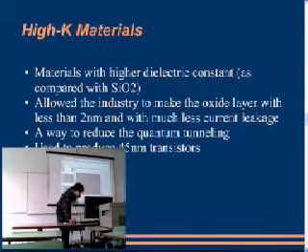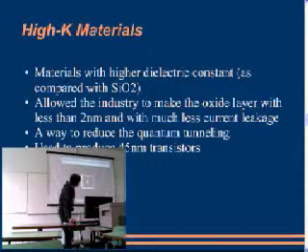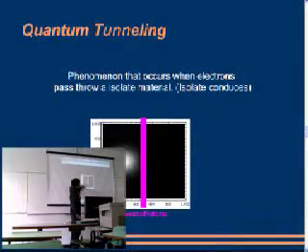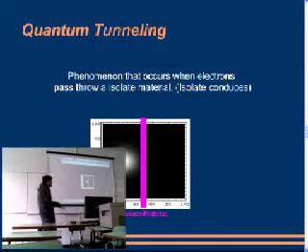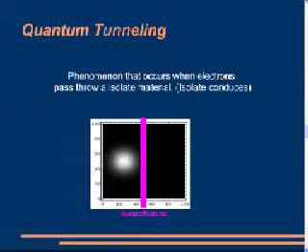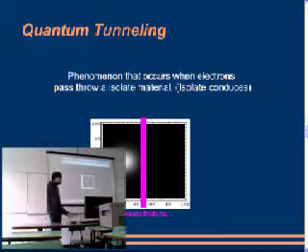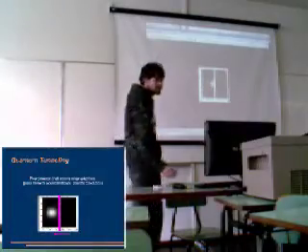Let me show you what this is. This is quantum tunneling. We have here an insulating material. We have here a package of electrons. And when this hits the insulating material, it passes through it, tunneling through it, quantum tunneling. And if we get a significant amount of electrons tunneling, we don't have a good off state in the MOSFET transistor. We have a leakage flow of current. This is not good. We lose power. We have more power dissipation with this.